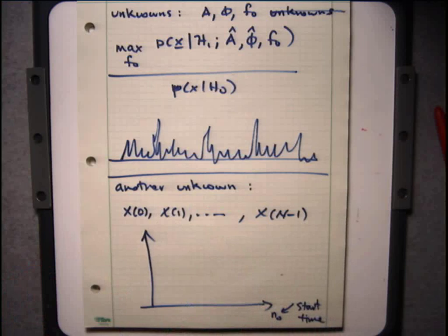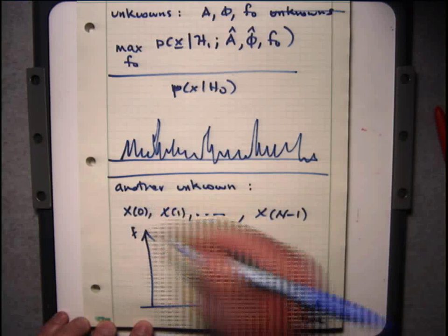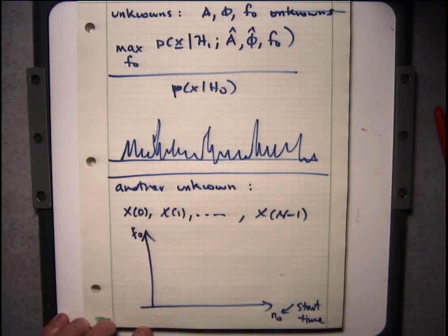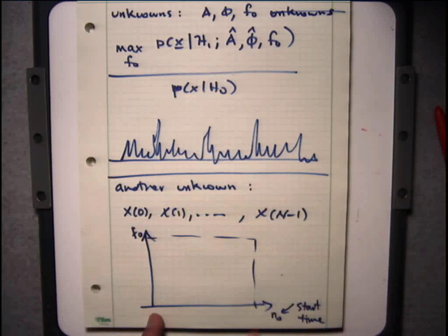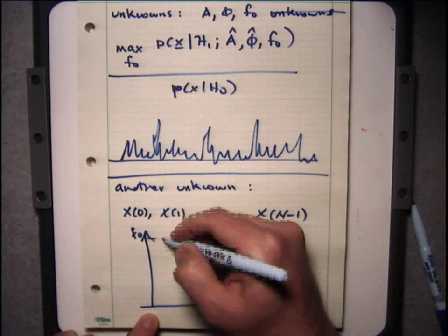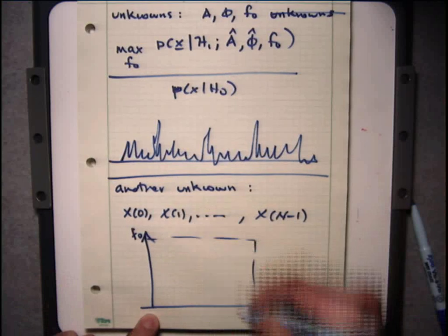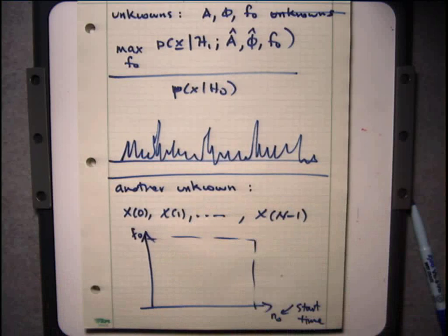Okay. You might also not know the end time, but let's put that aside for a second. So let's say you do a plot like this, where this axis would be the frequency, so let's say across different f0s. What you're going to get in this plot, you test for start times from 0 to whatever, 90,000. And what you're going to get here is a surface. Each one of the columns of this surface is going to be one FFT over a small window of, let's say, 10,000. And then you're sliding it across.